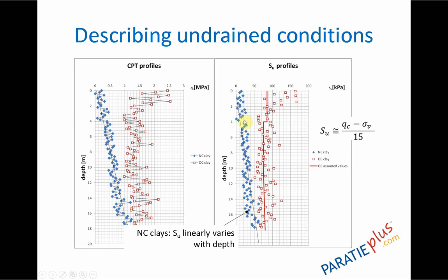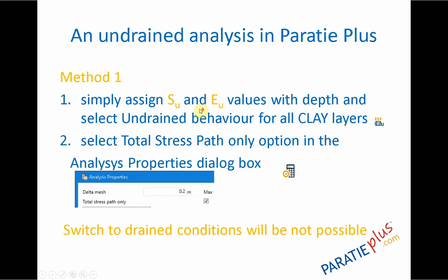We see that the undrained shear strength is essentially a linear increase with depth for a normally consolidated soil, whereas it may be constant or have a more complex pattern for over-consolidated soil. Of course, the undrained shear strengths for the same soil under two different geological histories reveal that the over-consolidated soil has a much higher undrained shear strength, especially in the shallow surface zone.